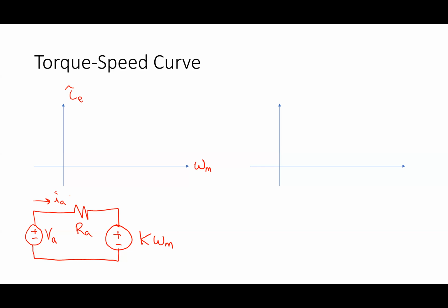It's hitting its limit no matter what voltage I put on here. It spins faster, but the maximum current this power supply can give me is 0.8 amps. So I can easily stop the machine. This is a stall condition: the machine is totally stalled out. It's producing as much torque as it possibly can, but I have put more torque than that on it, so it won't go any faster.